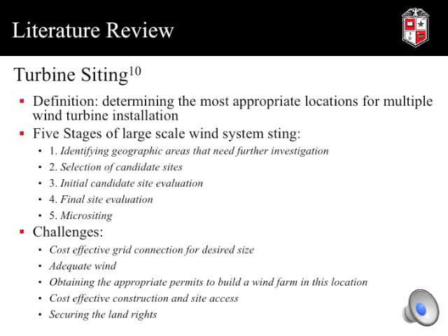When looking into a potential site, some general strategies are followed in industry. Initially, an area needs to have good exposure and low vegetation. Any hills need to be smooth with little slopes, as this can cause separation of flow. The area needs to be accessible, as complexity of the landscape can increase the cost. Lastly, the land needs to be available with few landowners.